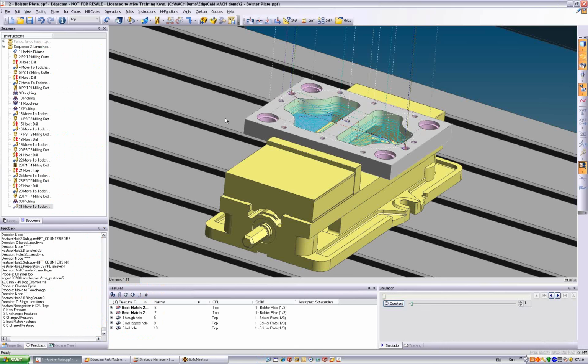But another challenge that programmers face is the need to change the machine tool. So in this particular case, we've just invested time and money in creating a FANUC style program. Now we've been told that this particular machine is out of service. Maybe it's had a crash, or there's a bottleneck in production, so we need to swap over the machine tool. So as a consequence of this, we have to reroute the part to a Cincinnati machine tool with a Heidenhain controller. So without Edgecam, this can be a very, very costly, timely experience.